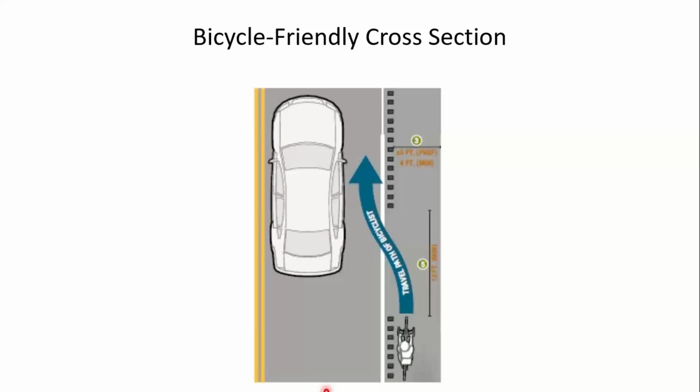And here you see an example. Notice this gap, 12 to 15 foot gap, probably spaced every, say, roughly 50 feet or so, to allow the bicyclist to move from the shoulder to the traveled way, or vice versa. They can go from the traveled way to the shoulder.